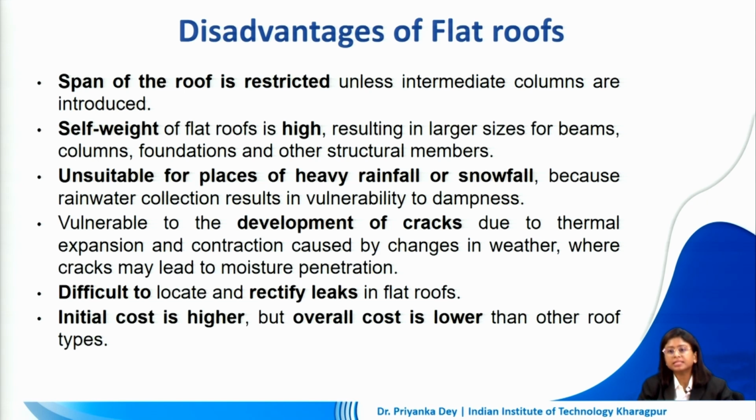It's not as easy as finding out one missing tile on a pitched roof and replacing it. A hairline crack which might have formed in a certain position will lead to penetration of moisture through that and will damage the internal spaces. It might be very difficult for us to locate it on the roof surface and repair it over time. But of course, one may note that the formation of such cracks doesn't happen very regularly. If there is proper workmanship done, proper terracing done, there is a fair chance for several years no such damage will be noticed.